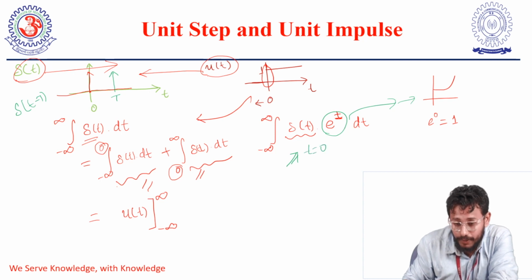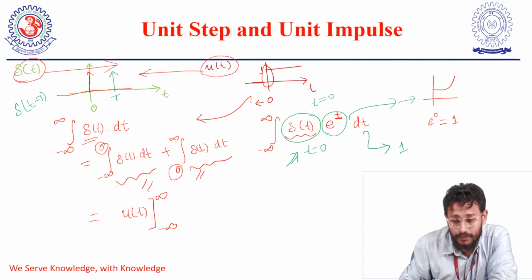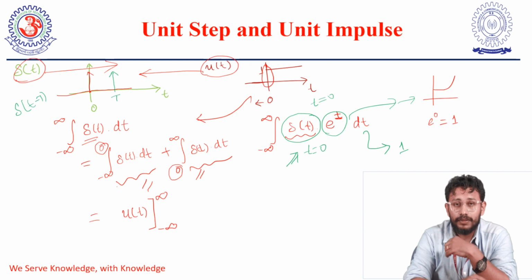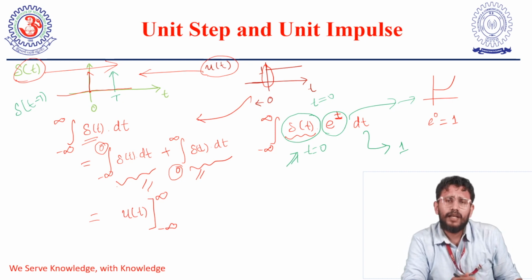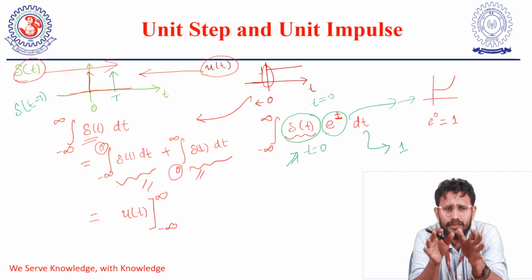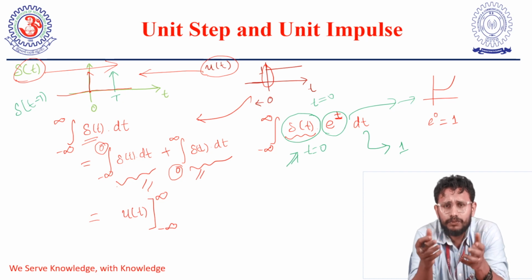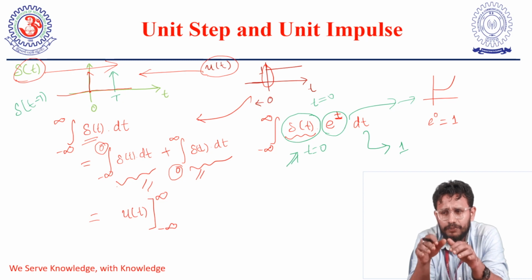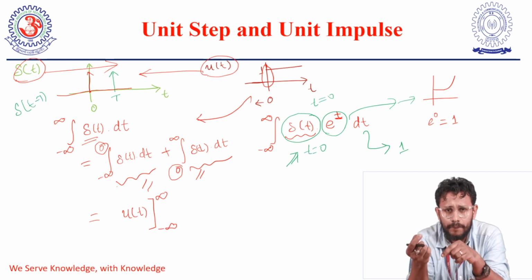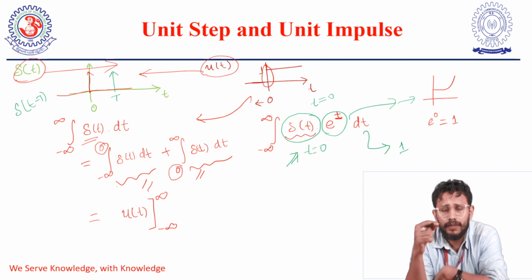And what will we expect about the output of this particular expression here? Since this impulse is existent only for time t equals 0, we'll be expecting the result of this function to be 1, because at time t equals 0, e to the t or e to the 0 is 1. So you would observe that multiplying, or getting the product of, the unit impulse with any sort of function will generally define the existence of that particular function at the duration when the impulse itself is existing.